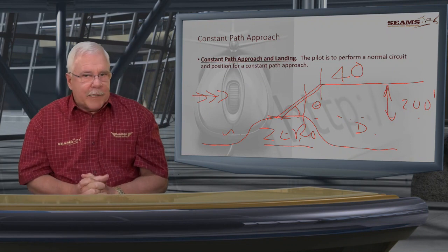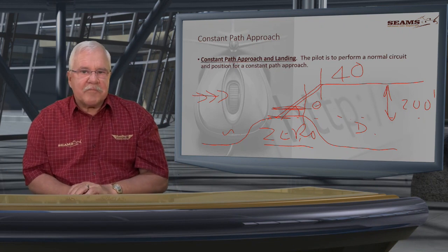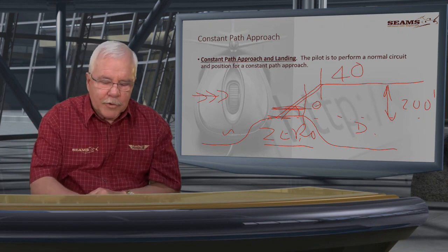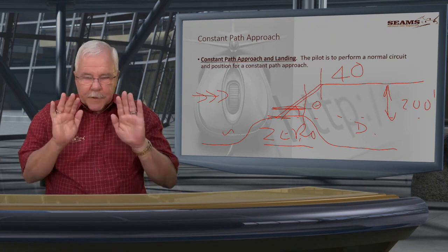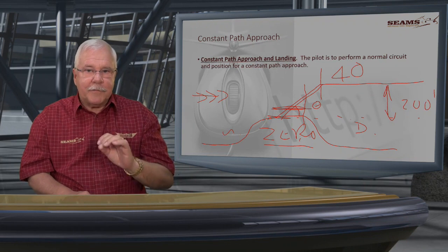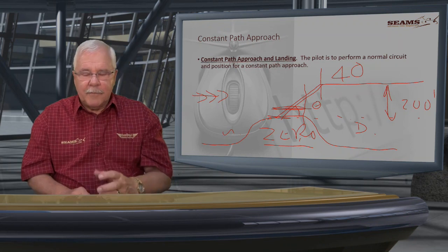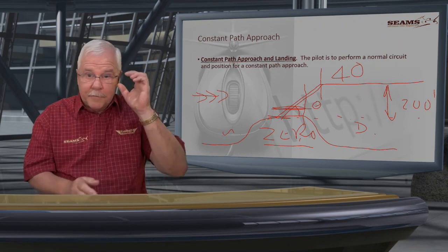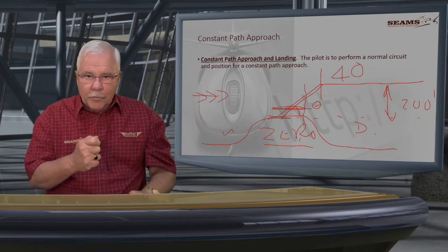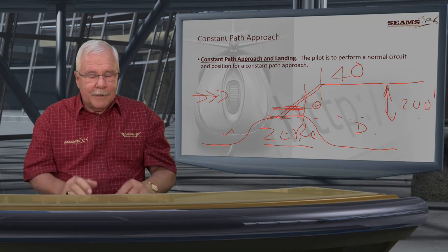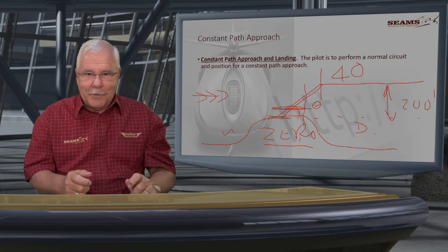Yes, I know, but sometimes we must get into the hover. Yes, we can get a little bit in the hover there if you want to check something out before you physically land, or you can't land or whatever. But you will find that if you do a proper constant path approach, your rate of descent near the end will come down. Remember, the limit here is 350 feet rate of descent, which is only with the collective, and the over and undershoot is with the cyclic. You're all going to try and do it all with the collective.